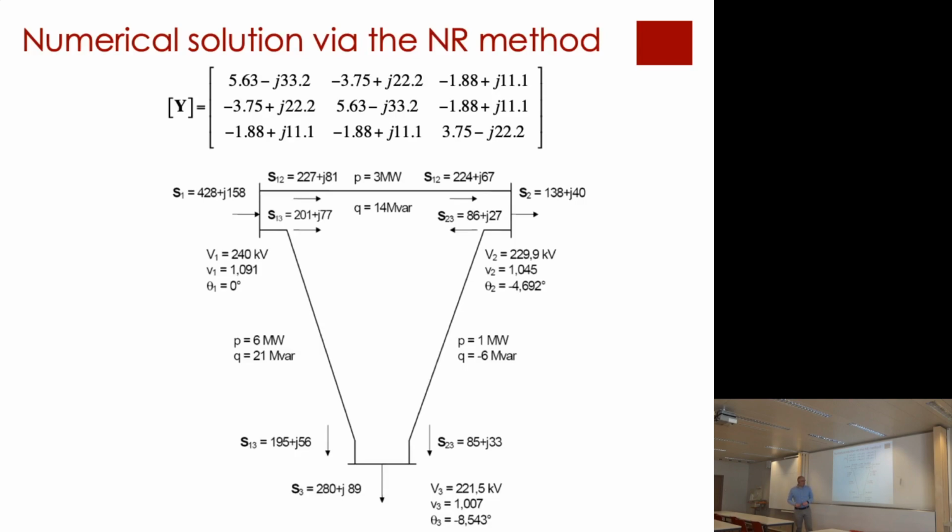So what your colleague was saying is, what if we get bad operating conditions? For instance, the voltage at this node is below the threshold, let's say 10% below the rated value of the voltage. You have to do something. You have to either change the nodal conditions in terms of active and reactive powers absorbed in your system, or change something at the slack bus, which is increasing the voltage. You have to take counteraction.